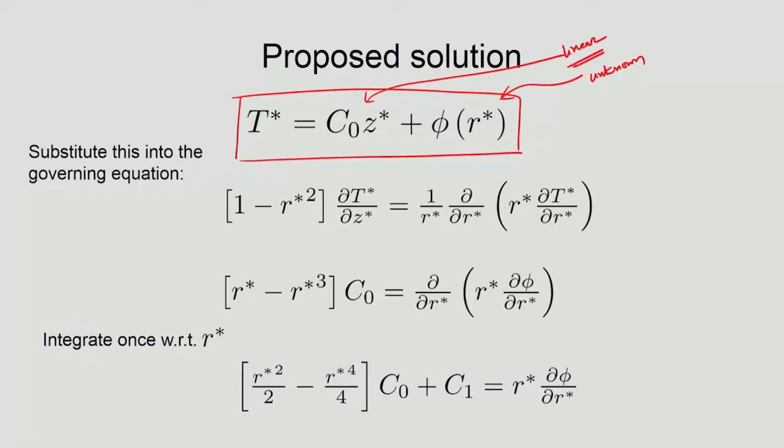So this means that the temperature variation along the tube due to the heat flux from the surface is going linearly as a function of z star, but there is a correction term that is coming because of the phi, which will give you the temperature variation along the r direction. So this is quite natural, and it is also intuitive, the way we know how the pipe flow will be affected by heat flux from the surface.